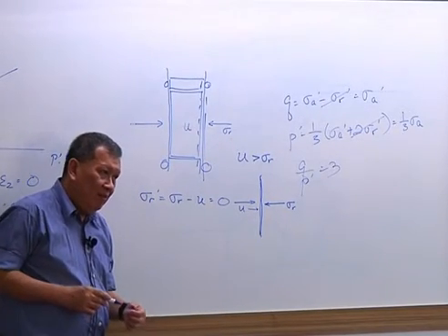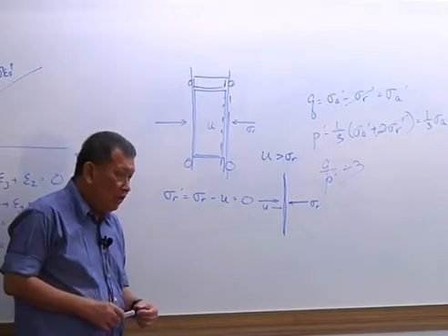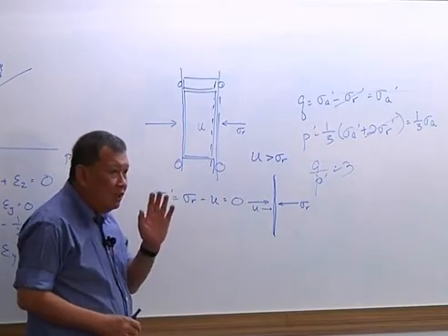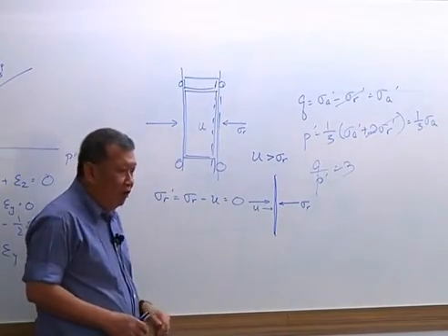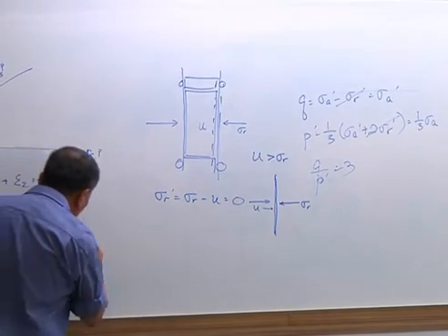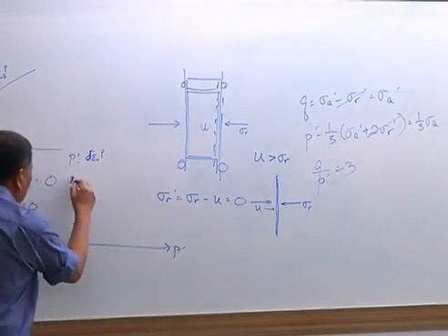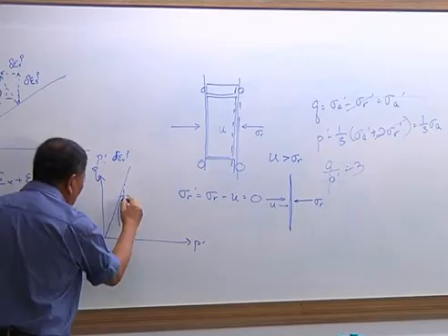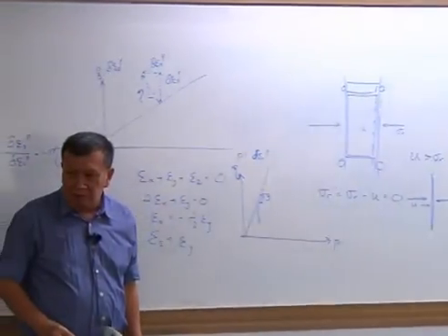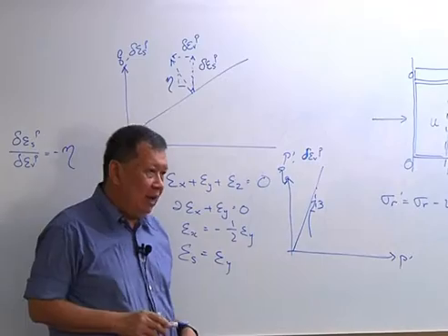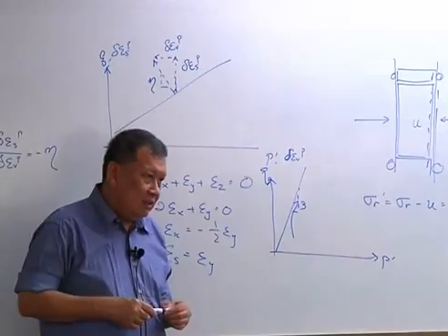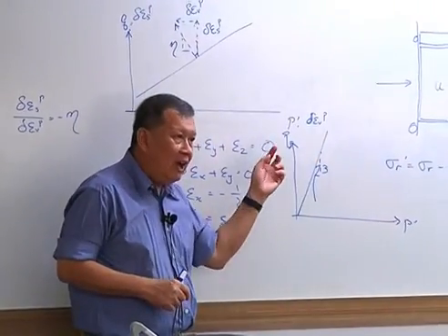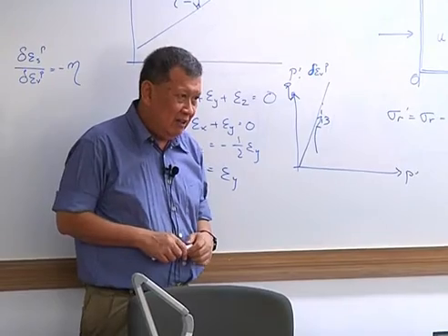Okay. So if you ever develop a condition where the soil sample is getting close to this, you'll find that your stress path will naturally not go there. It will just go along that particular line. Basically, there's a particular line over here, in p' and q. This is 3 to 1, where all the soil stress paths will try to move along once you reach it, because it just cannot go beyond there. That is the limitation of the triaxial test. And that is the reason why this portion here cannot be explored with the triaxial test.